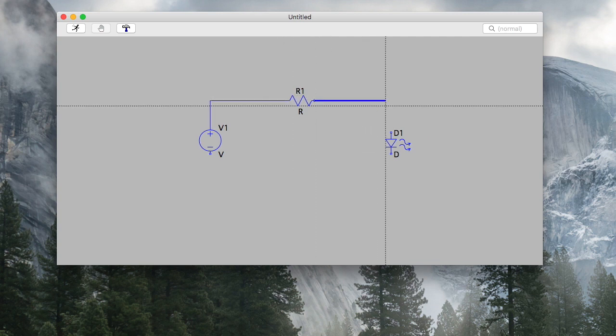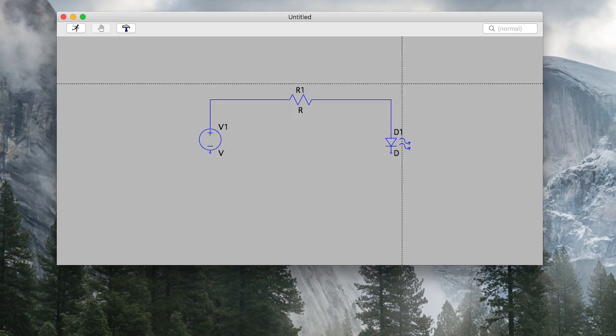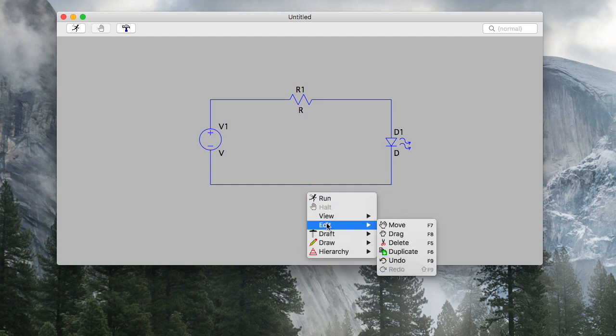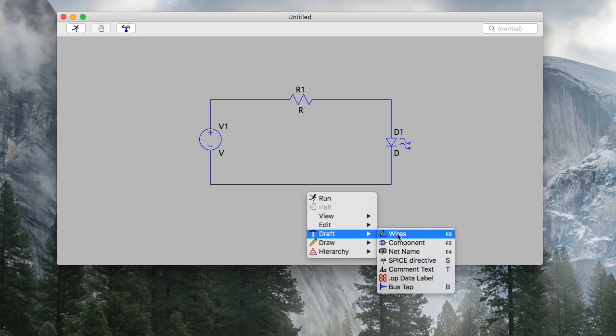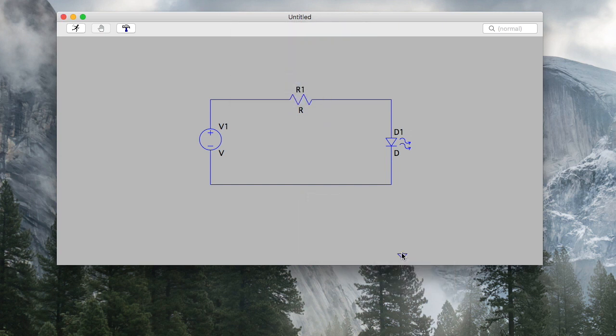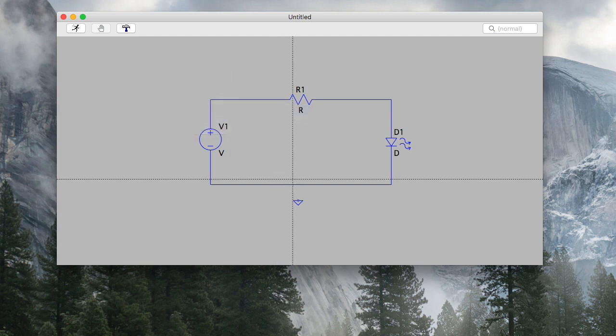I don't run them at 35 milliamps. I run them at half or less. That's very bright. And plus, the 4017 is not going to support driving that much current. So we're going to find the optimum value to drive it at approximately, I would say, 7 to 8 milliamps to 15 milliamps. Optimum, if I was using a TTL driver that could actually source more current, I would probably hit the mid-range between the specified average forward current, because that's pretty bright on these LEDs for a toy.